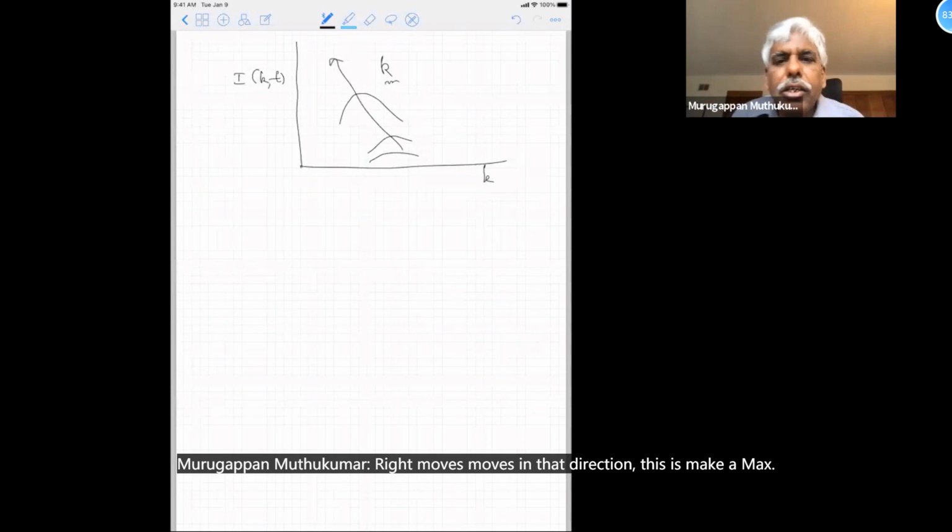So what I can do is, suppose I plot the logarithm of K maximum versus the logarithm of time, you'll see this is an early regime where it does not change. Remember, this one does not change at all. This is very early times. When the nonlinear effects come in, this will coarsen like this. And one can show that here your slope is 0, here the slope is -1/3. Okay. So that's the discussion of spinodal decomposition.